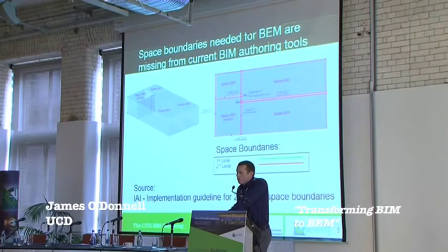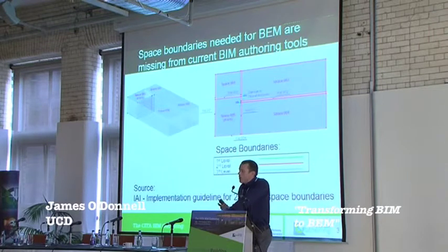But in the interest of enclosure, and again these simplified heat transfer models, we also see here the third-level space boundaries. These are cases where heat transfer is not possible in the context of the simulation engine, and these must be included in the energy simulation model for zone enclosure, and these are represented as adiabatic surfaces.